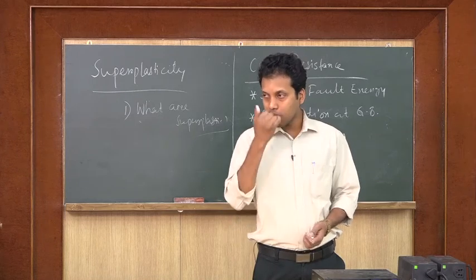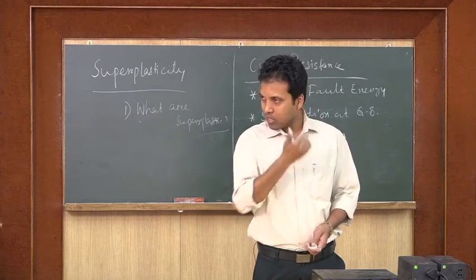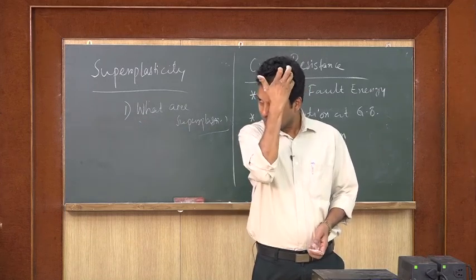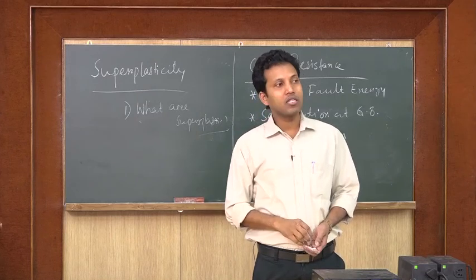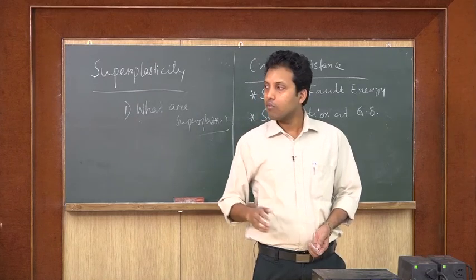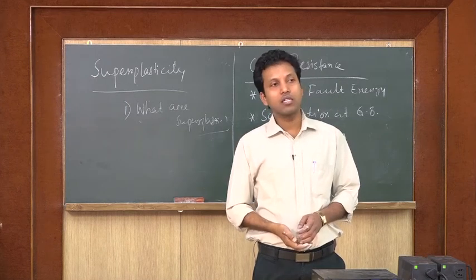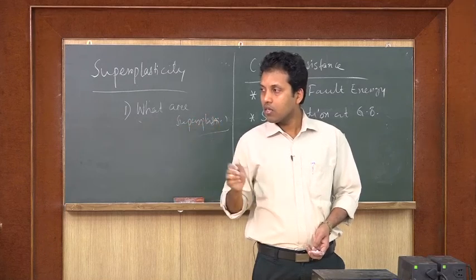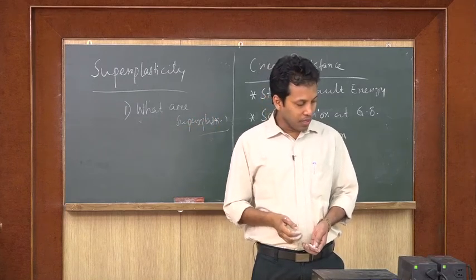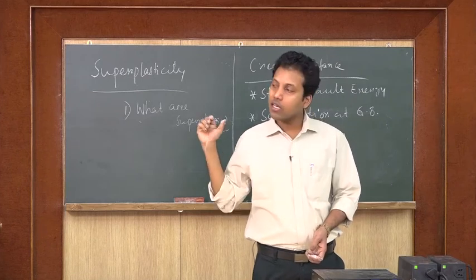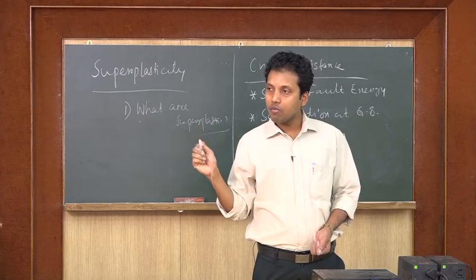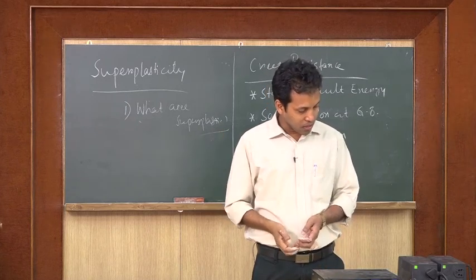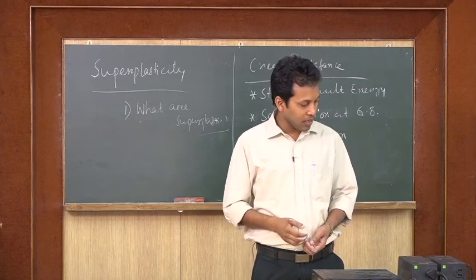Similar to that, some dispersion strengthening. Dispersion strengthening means some dispersions can be put in a material in such a manner that they can hinder some grain movement. Here we have diffusion and grain boundary associated with creep deformation. So, if I can have some segregation at the grain boundary, then there will be improvement in creep resistance. Another one is fine dispersion, as I said, similar to that.